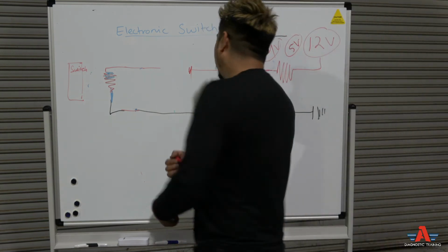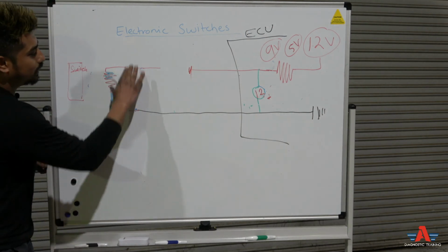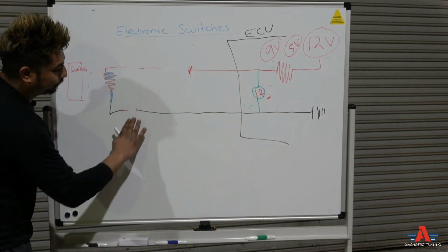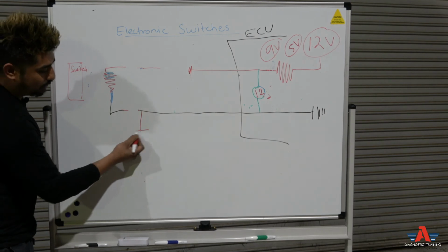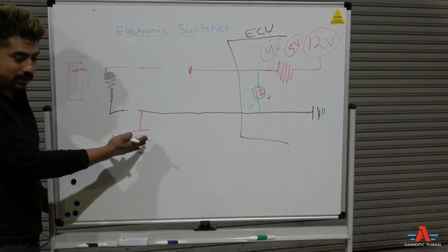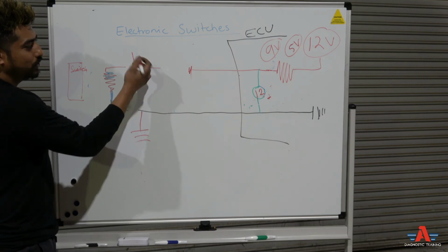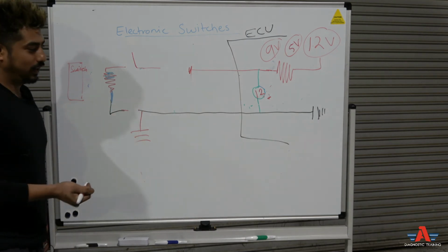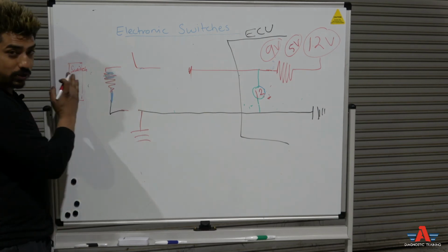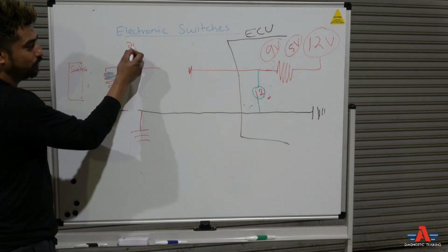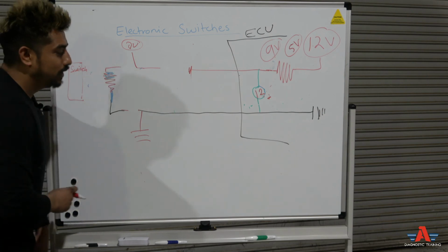Now, in that case, if you disconnect the connector right here and you saw ground, yes, test light lights up, you saw ground, and you put your meter right here and you see nothing. Okay, disconnect from the switch, obviously you saw nothing, 0 volt, right?